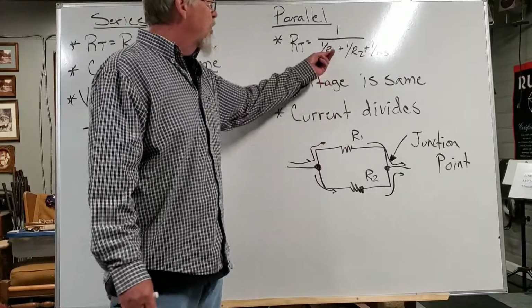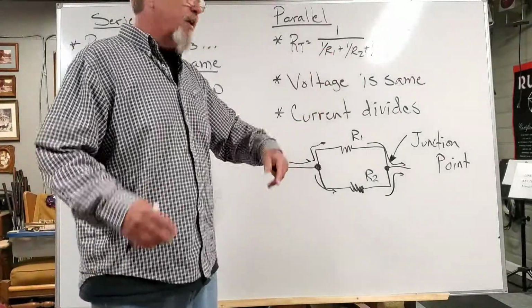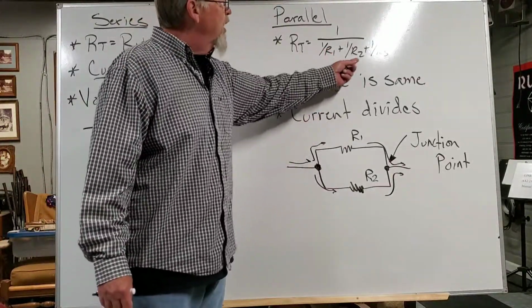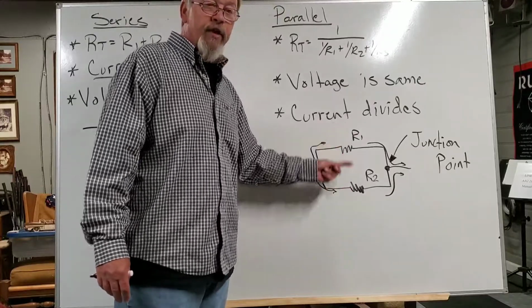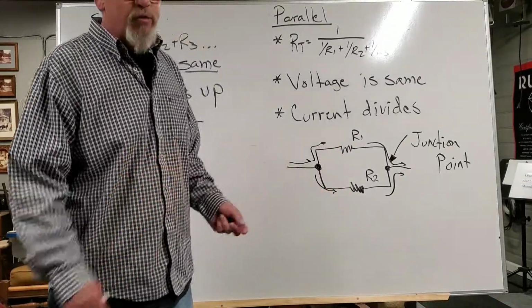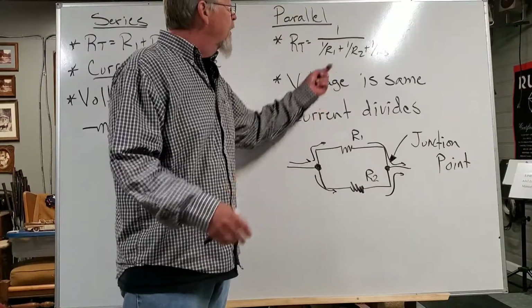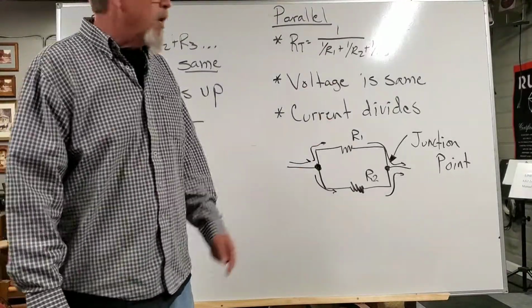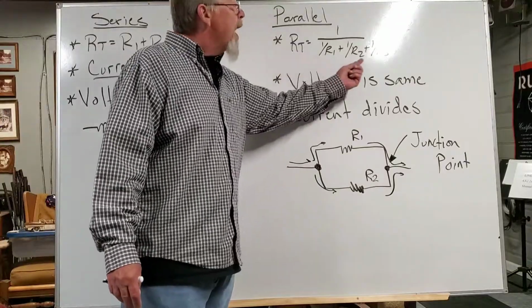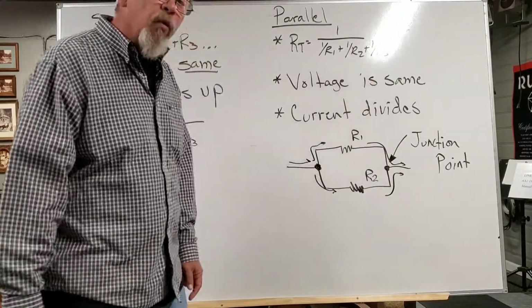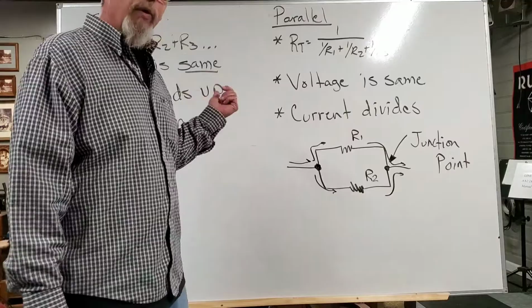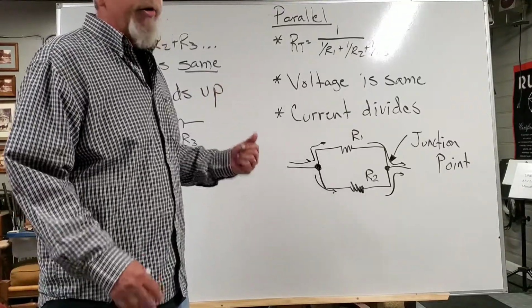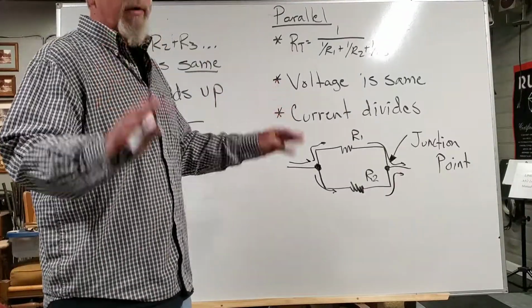So we invert the resistance value to find the conductivity. So we're really just adding up all the individual abilities to allow current, and then at the very end we're going to 1/over it back into resistance. So in parallel we add up resistors the 1/over way. In series we add them up the regular way. You've got to know this. I mean, straight up know this.